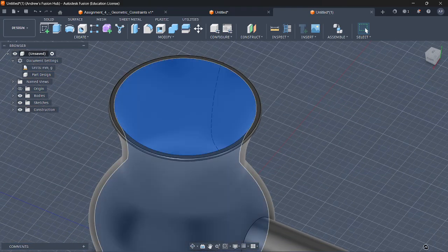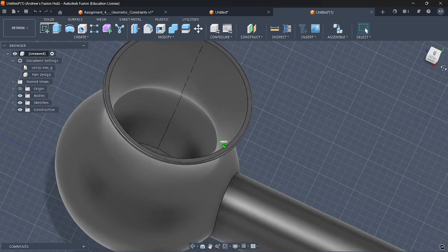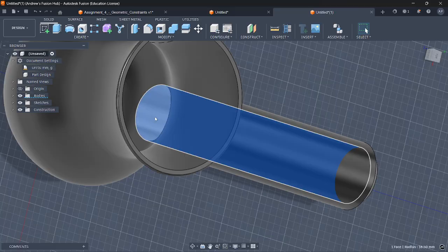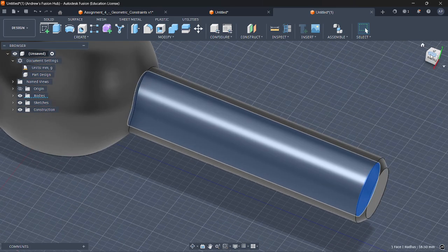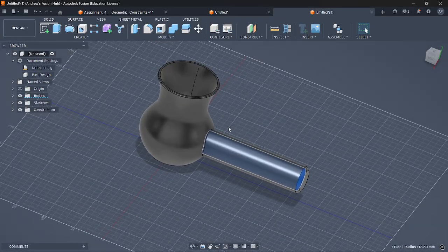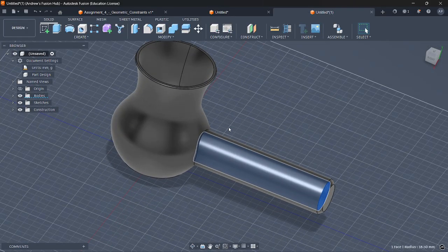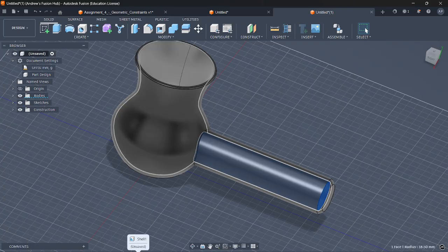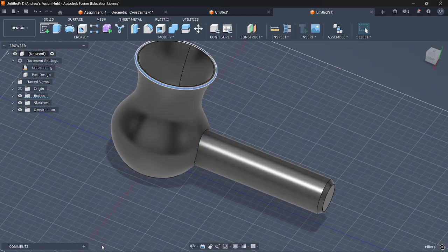And if I want to move the shell, it's going to let me now. You can see the line is dragging with me. And when I let go, and I rotate over here, you can see this area is now hollowed out, right? So this is kind of what I'm going for here. Now we can put stuff inside of it if we wish to. But this can be kind of important if you want to change your timeline later, right? If you ever move things but it's not letting you progress it, you typically need to find that dependency. In this case, for me, it was that fillet there.